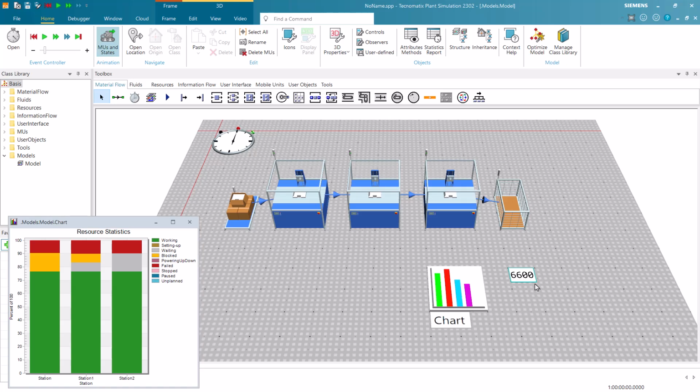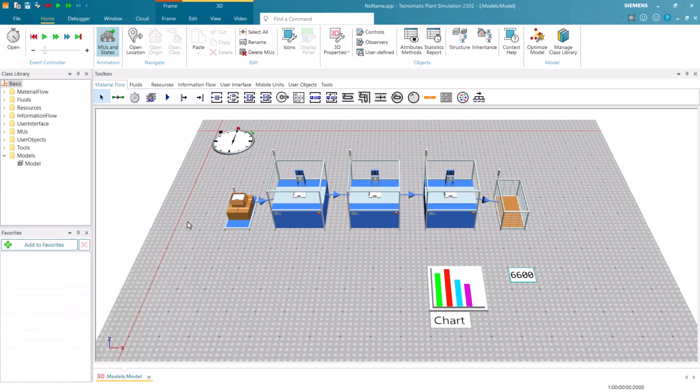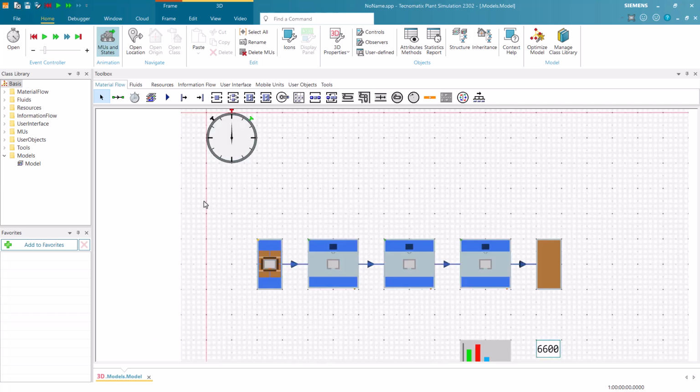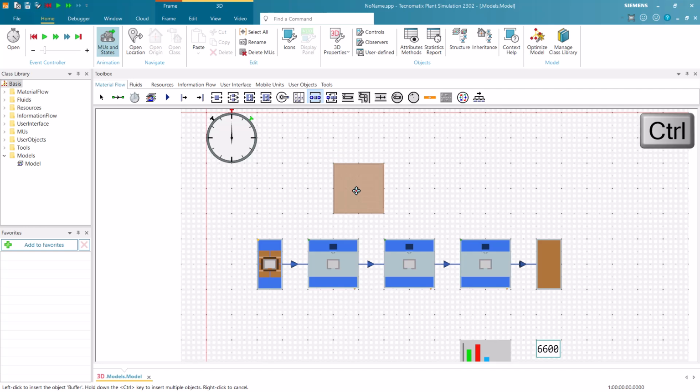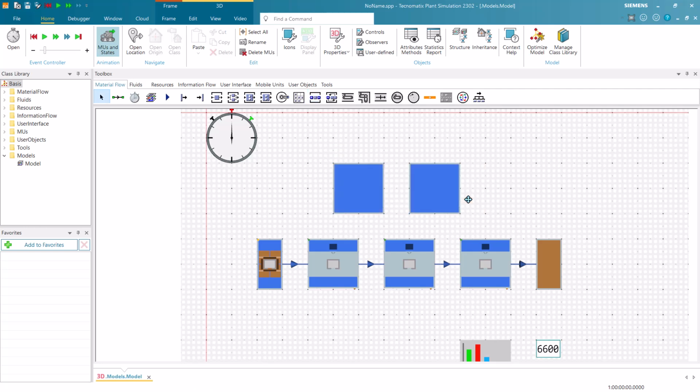To reduce blocking times for machines in production lines, buffers can be used. To do so, insert a buffer between the stations and adjust the connectors. The buffer not only tides over failure times, but also serves as a compensating station for fluctuating transport and operating times, which lead to queues forming in front of a machine or a component.